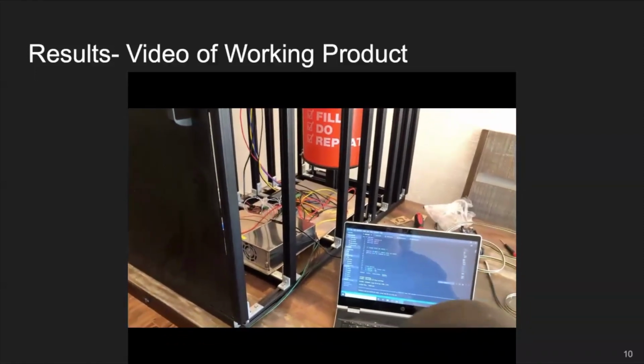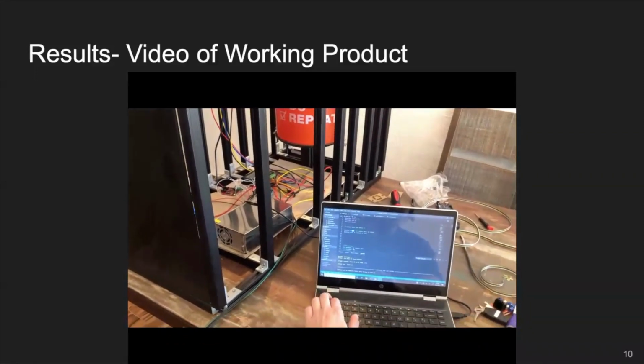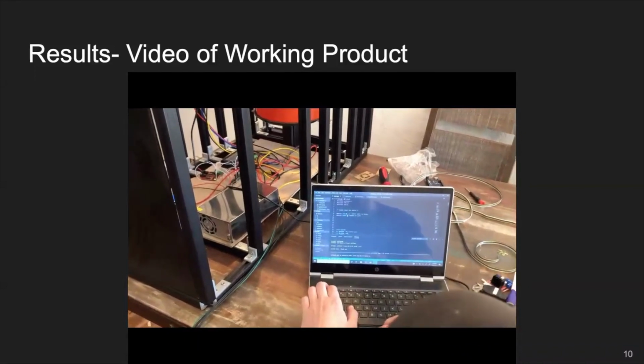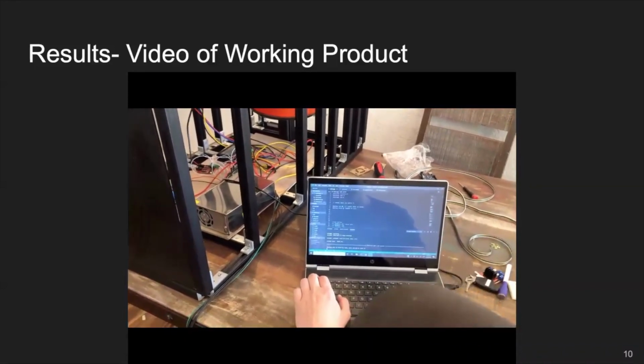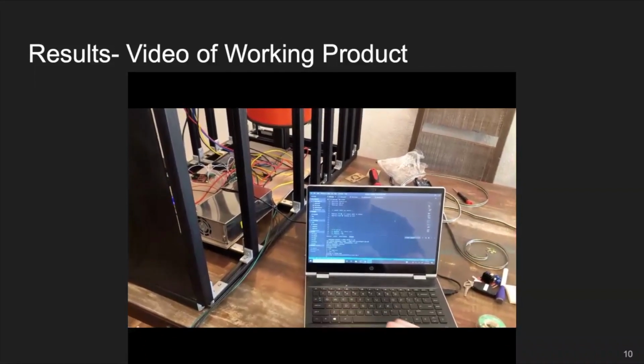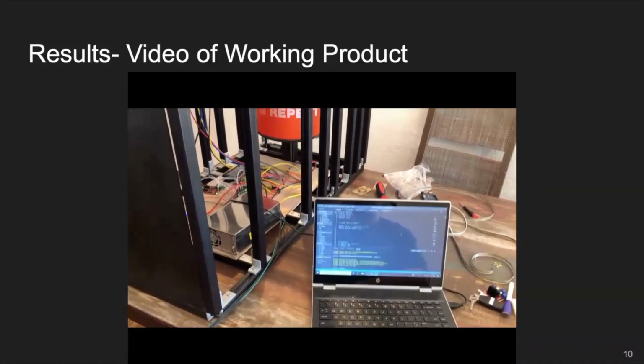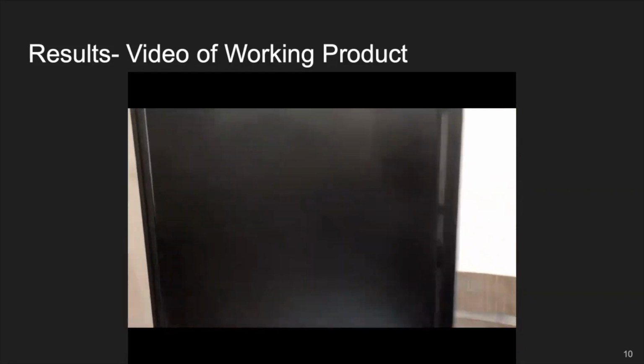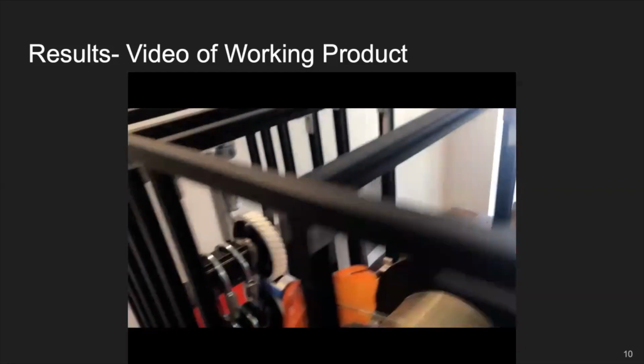Right now it's waiting for the input to be changed. We're going to do 60 inches, which is 5 feet, for 2 counts. Then you go down here, you press this upload button. After that, it should take about 3 to 5 seconds for it to start. It might jolt a little bit to make sure that it's initialized, and then it'll start going.